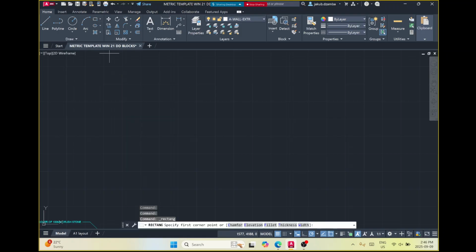I'm going to click on the drawing area, and now I'm going to type at. So hold down shift and number 2, so the at symbol, and I think it was 490 by 150. So I'm going to type in 490, 150, enter.